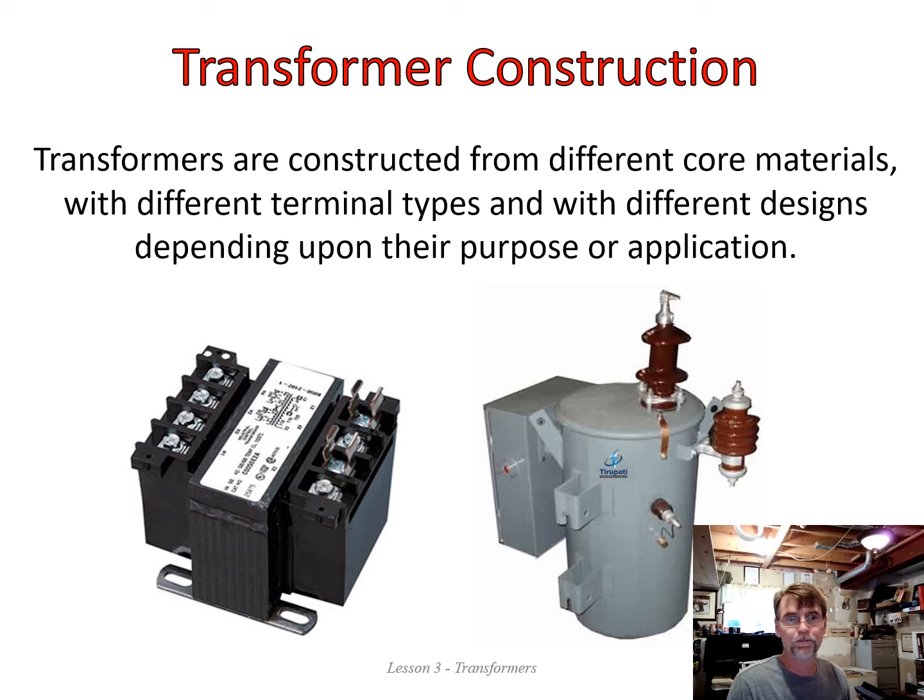So again, all kinds of different variations. We have images here. We can see lots of different constructions. Different core material becomes part of the conversation. That one equation that Pete showed you talked about the permeability of the core within a coil, and that is part of the equation. That equation was to determine the inductance of an inductor. So the core material is definitely a relevant part of the conversation when talking about transformers.